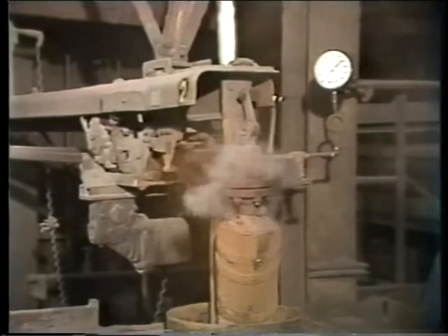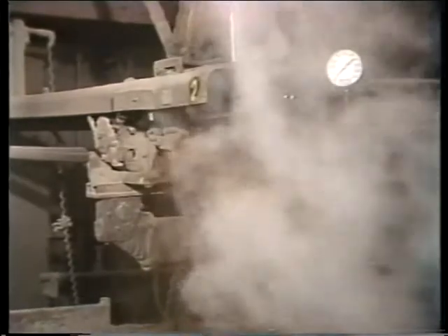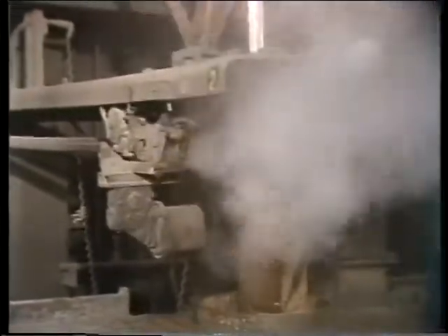Excessive leakage of the blowing medium can be dangerous to anyone nearby. Leakage can occur during the blowing cycle if packing of the feed tube and element or if valve packing allows leakage. Leakage past the valve can occur when the soot blower isn't operating, if the valve doesn't seat properly, or if the stem binds.